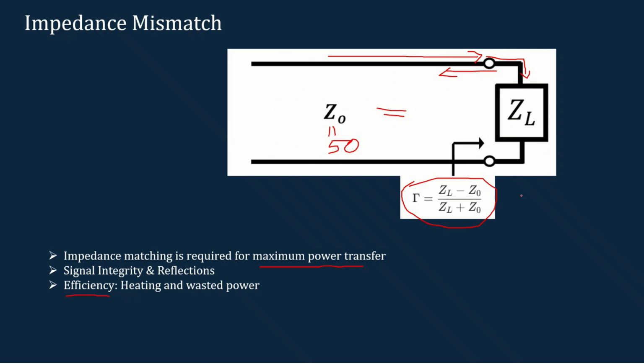Suppose we have designed an antenna in such a way that all other characteristics like bandwidth, gain, and radiation pattern are satisfied, but the only thing is that the input impedance is not matched to 50 ohm. In that case, it is not always required to redesign the antenna to have the impedance equal to 50 ohm. So in that case, what can we do?